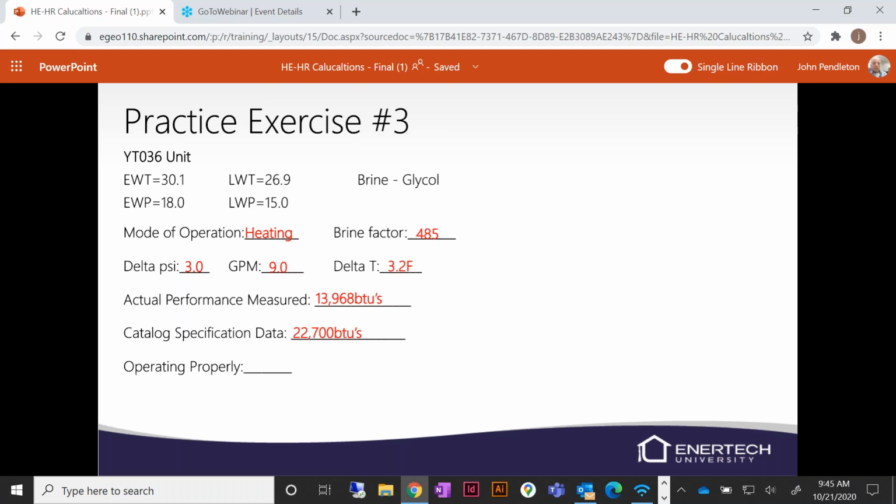If it does, make sure that it's shifting from first stage to second stage. The easiest way to check to make sure a compressor is changing stages is amp draw. It should go up usually about 3 to 5 amps based on the tonnage of the unit between first and second stage. So you can unplug the solenoid or remove the Y2 call and see if that amp draw changes. Your pressures will actually be a little bit lower in second stage than they will in first stage. Basically, without getting too much into the compressor today, there's an unloader when it's in first stage. So it dumps refrigerant back into the suction in first stage. And so that's why you've got higher pressures in first stage than you do in second stage.